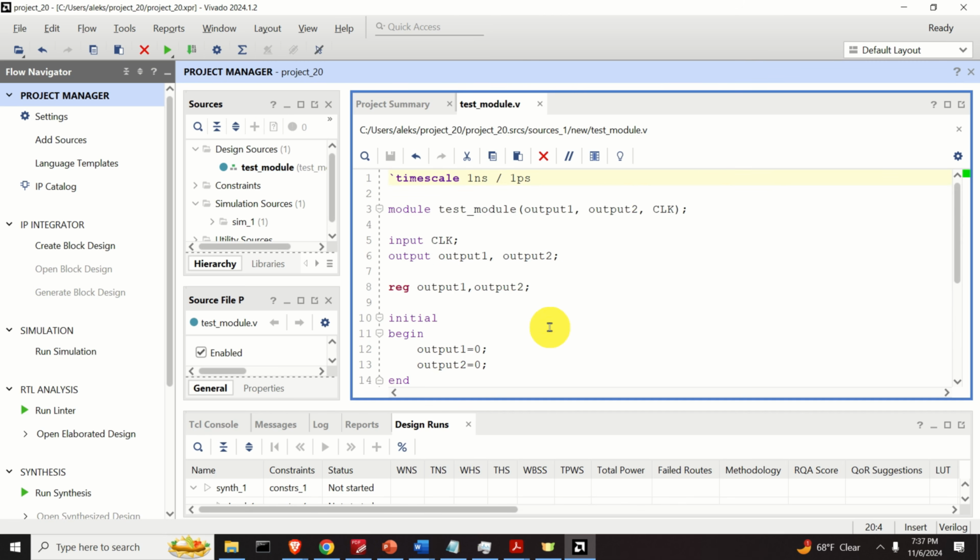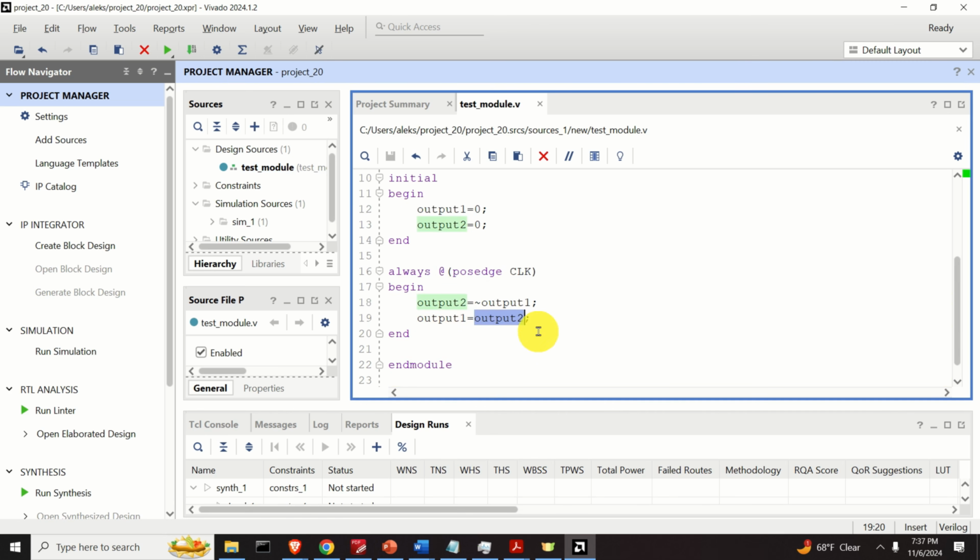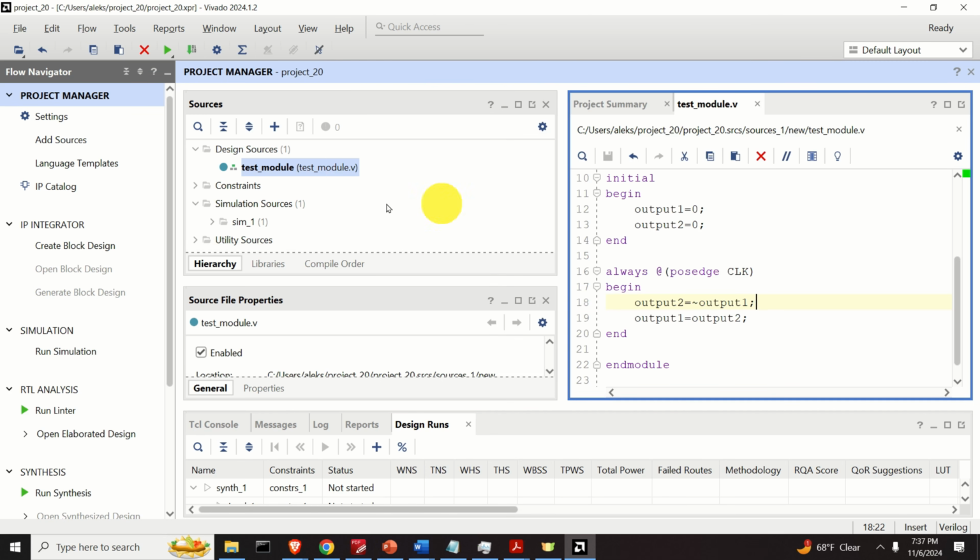Let's make sure that there are no syntax errors or some other errors. Often in Vivado you will see a syntax error, or even this nice environment will be able to recognize a compilation error, and you will see a red line below the text. However, we don't see it over here, which means most likely everything is fine. The next step is to define our test bench file. So let's do it. Let's change the size of this window.